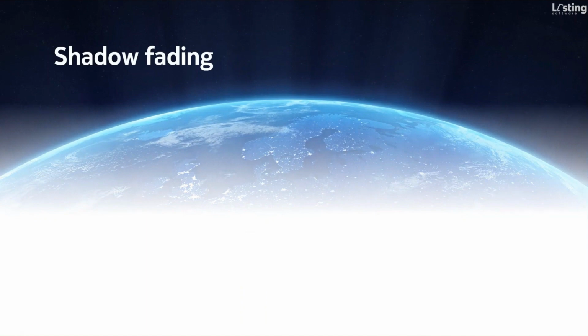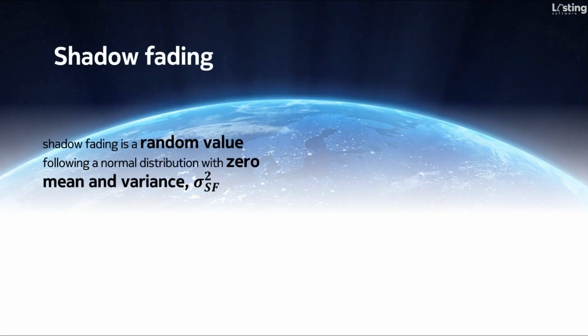Shadow fading, or SF, is a random value following a normal distribution with zero mean and variance as per 3GPP TR 38.811 v15.1.0, namely the study on new radio to support NTN networks. You might also be asking about clutter loss. Well, clutter loss value depends on the propagation scenario, satellite elevation, and frequency band. Henceforth, only line-of-sight conditions are considered, and clutter loss can be ignored.